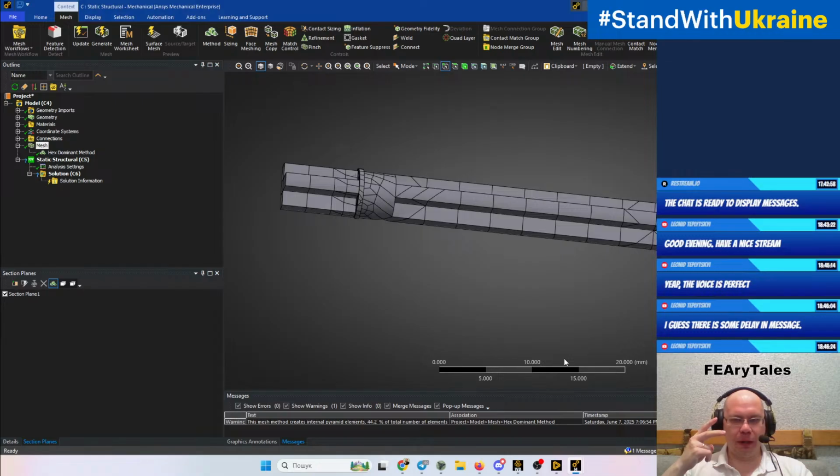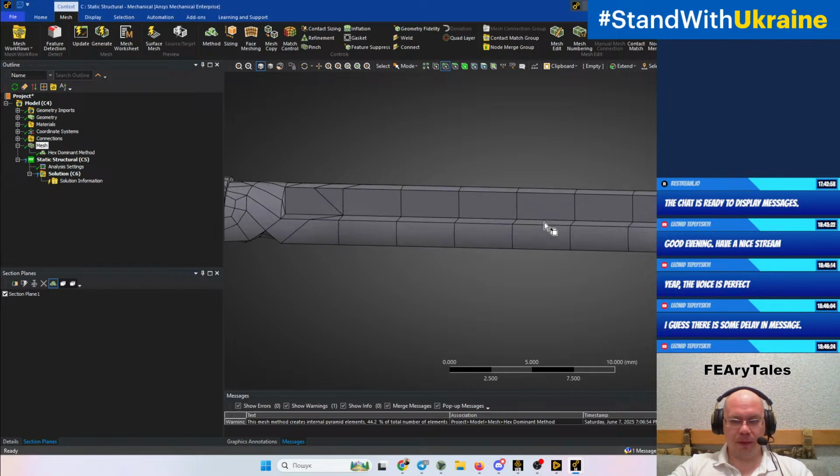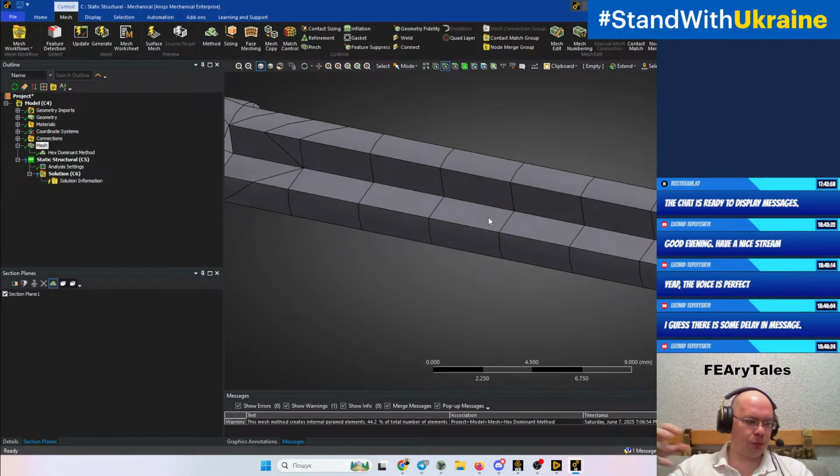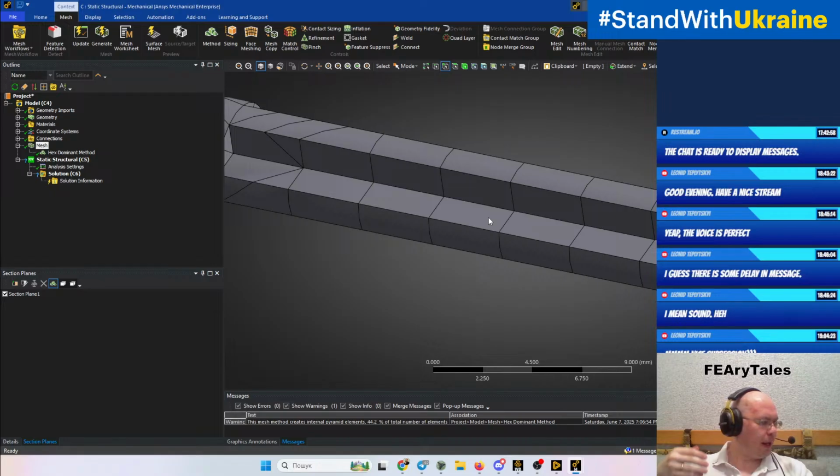It can work by two main types. The first approach is to create the tetrahedral mesh and then split those elements or unite different elements into hexa and then apply some smoothing to obtain better elements. That's the first approach. And the second approach is when we take our object, and we create the quad mesh on the boundaries, on boundary faces, and then